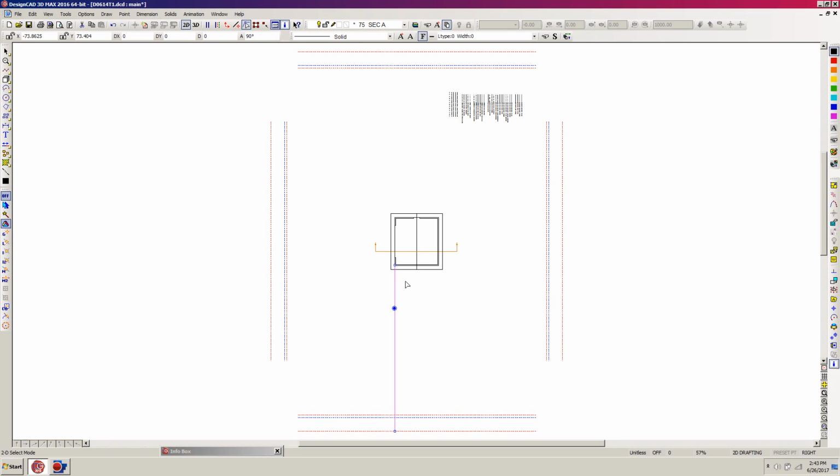What I want to do now is bring the top of this line down to the ceiling level. So I'm going to hit the line extension command, which is Shift and dash, and then you left click on it, and you can see how it moves the line, either extends it or reduces it. And I'm just going to get it down fairly close to the ceiling line and then left click.